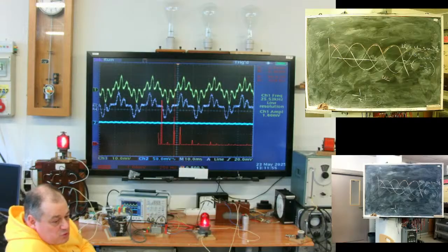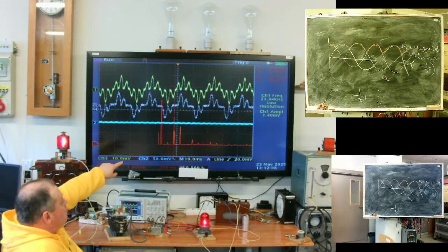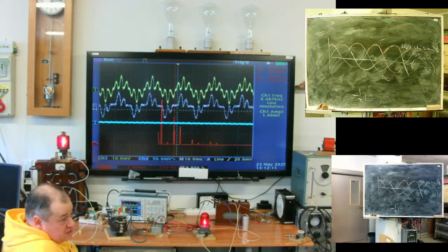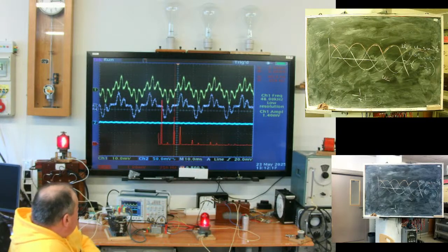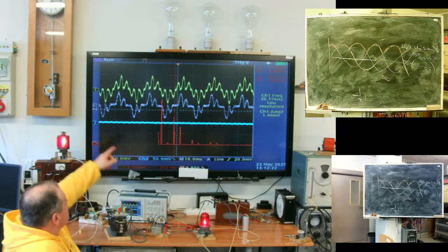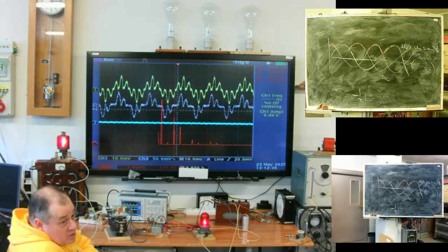This one is the most probable picture on the middle voltage side of a powerful inverter. This high frequency component will destroy your power correction capacitor, will eat insulation of your cable. This will become a problem. Possibly you will need a filter on the primary side. This is the problem you will see with high power loads needing a DC source.